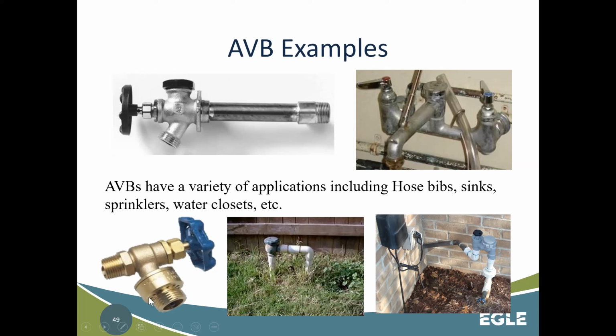And as you can see, these little holes around the rim, what they do is they don't allow the water to come back through from a garden hose, even if there is a downstream valve, because it creates somewhat of an air gap here and it blows the water out here. Under normal flow, it just flows through. But once this valve's closed, it just kind of sloshes out here around it.